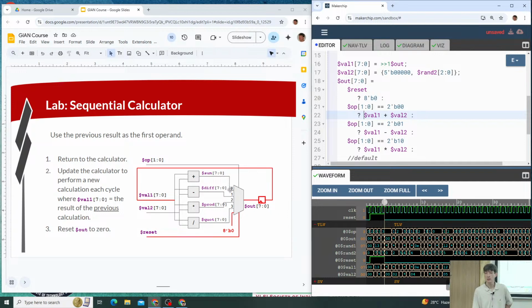Yeah, so logic synthesis, it's possible that the library that logic synthesis is working with has perhaps a 4-to-1 mux. Generally, it's going to be working with lower level things. But it's up to logic synthesis to take the logic as we've described it and map that to the physical cells that it has available. So this doesn't mean there's a 5-to-1 mux cell. It just means that's the logic function that we want, and then it's up to logic synthesis to make that happen.